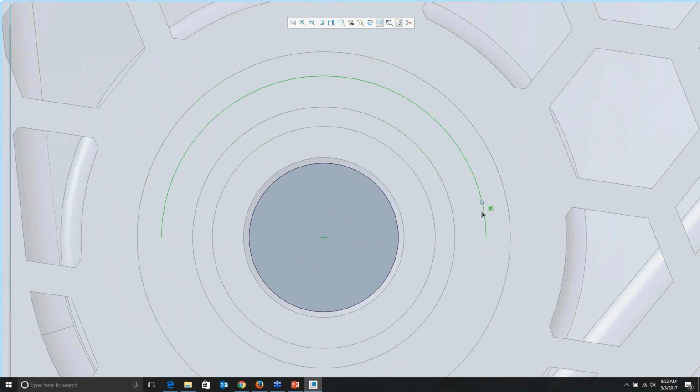Well, now with Creo 4, I can just as easily put my mouse over what I want to be a reference, and Creo 4 picks up on that. And now you'll notice those three yellow dots, and also this yellow dot in the middle here. Now it thinks I want to use the center of that circle as a reference. And I say, yes, that's exactly what I want, and I want to snap it to that existing circle that I picked as a reference, right? So automatic reference selection without me having to go to the reference box and pick it myself.